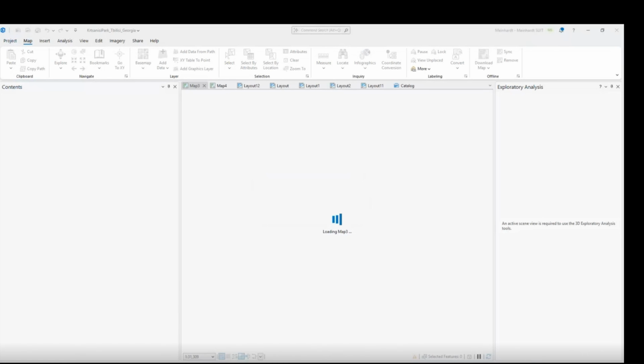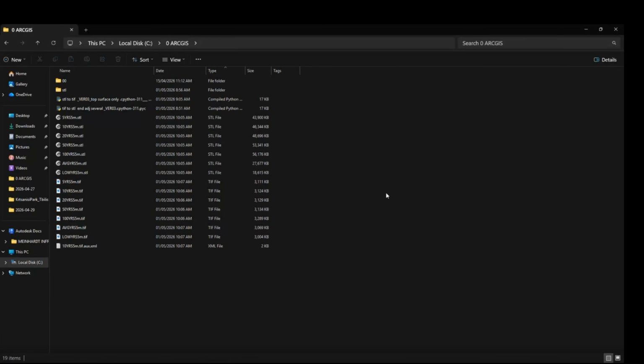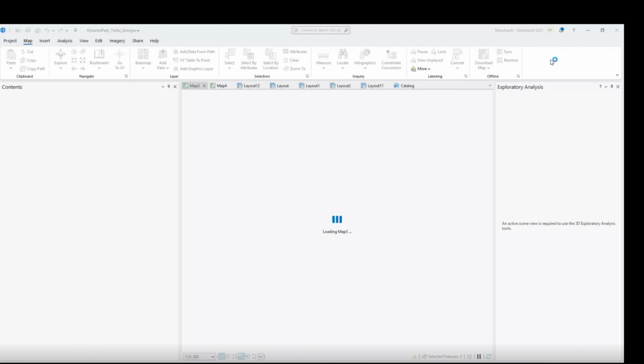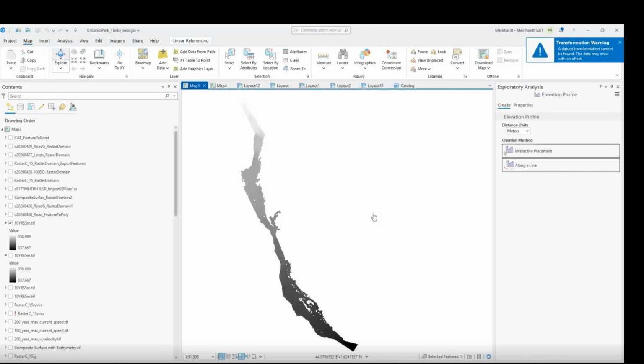In this case, scaling is not impacted. Normally, when we use georeferencing, we need 4 points with proper projection. Here you are just using 1 point and moving the entire file from 0,0, because the X or Y in their files are shifted, but they still have the same orientation.